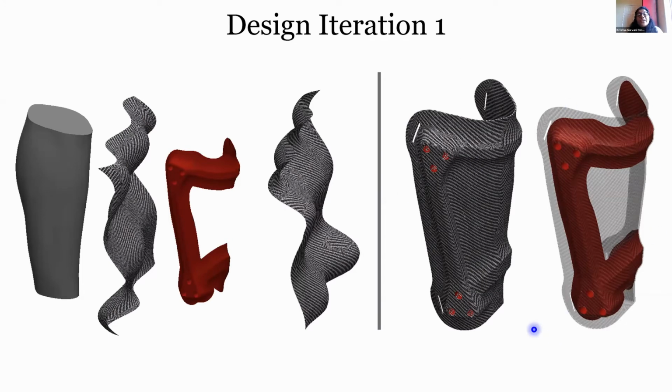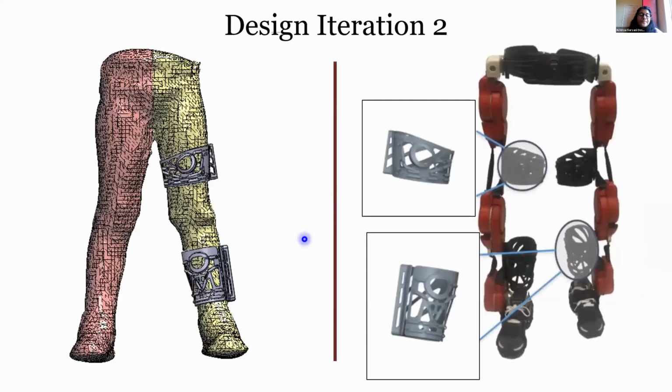Now, this process was great because the 3D scan dimensions made it more accurate than using simple manual measurements. However, the process took a long time, and the use of external carbon fiber layers and the epoxy could reduce the form-fitting nature of the brace. Because of these considerations, as well as the decreasing cost of 3D printing, we made the decision to transition to an entirely 3D printed brace.